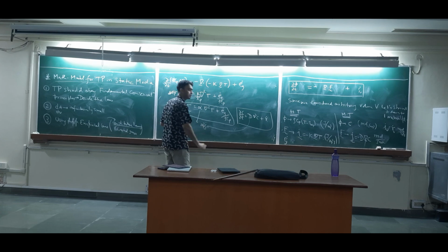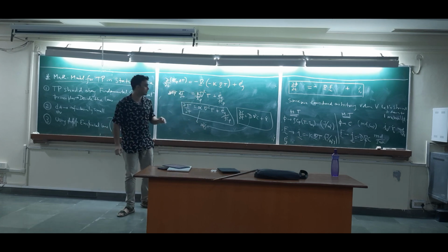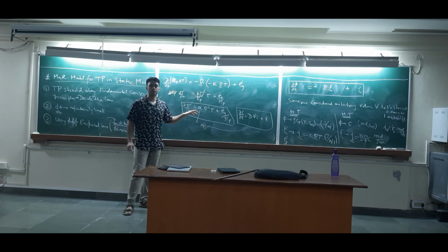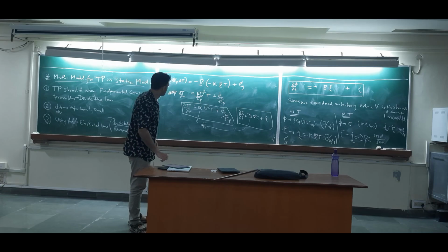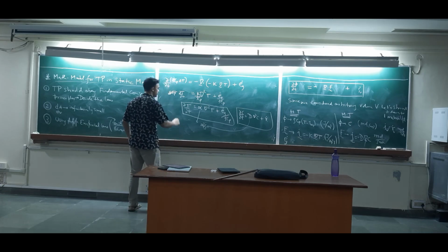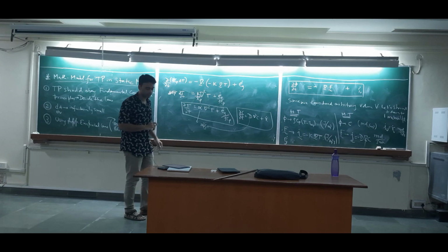Meter square per second. You remember in one of the lectures I said that it's not K that decides your spread of temperature. Alpha specifically decides your spread of temperature. That you see now clearly, right? So this alpha governs the rapidness of temperature spread and concentration spread.